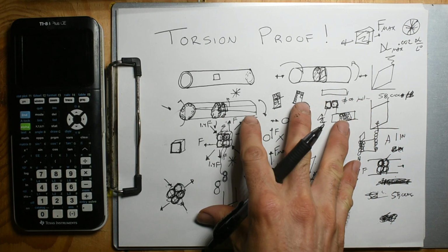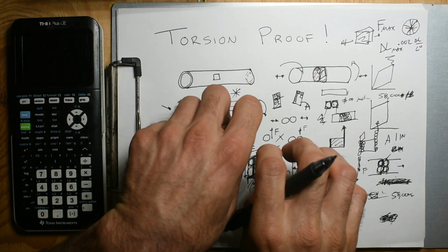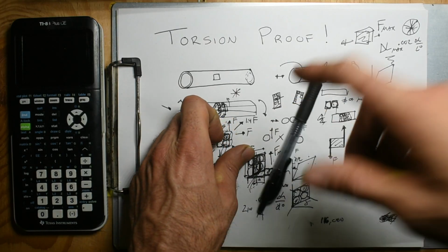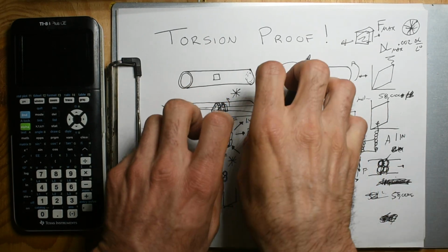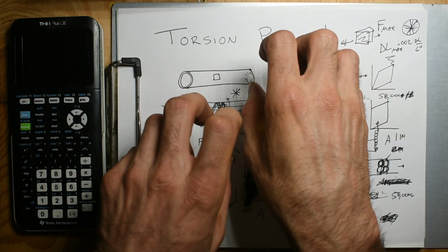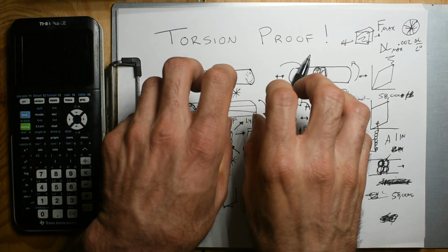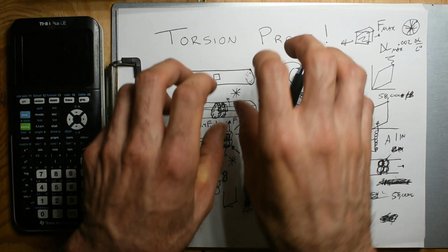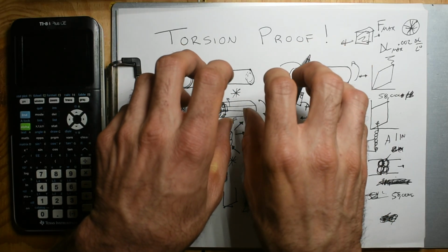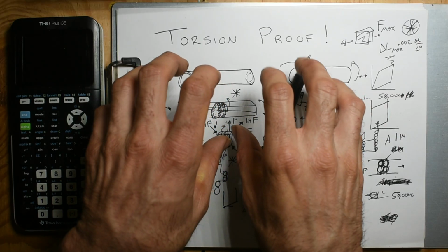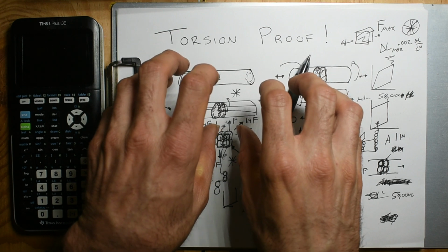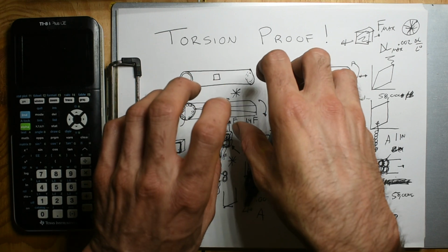What happens for the torsion proof is that molecules can only get tweaked a certain amount before they reach their max. And that's the linear range. The second they get tweaked out, if you go farther, then they get plastic and they'll stay that way. If you tweak them out a distance of, let's say, you can go a distance of 2 and then let go, and then all the molecules go back to original shape. That's kind of the fundamentals of material mechanics. This is the linear range. Let go and they go back magically to the identical location. So this was a distance of 2, goes back.